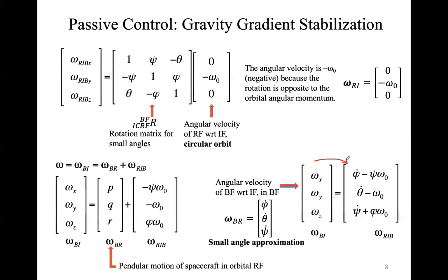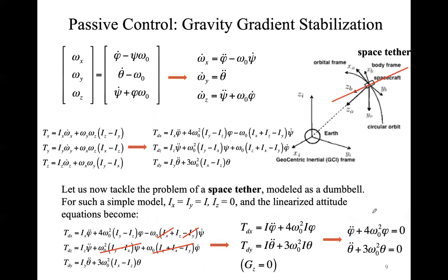We can substitute, and tomorrow you're going to see it better, the vector omega of the body with respect to the inertial reference frame with this expression of phi dot, theta dot, and psi dot, and also the angles yaw and roll. First of all, we can also take the derivative of omega in order to determine omega dot as a function of phi, psi, and theta.